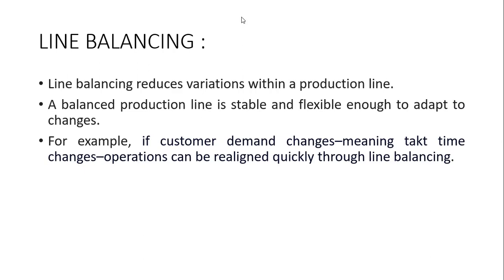According to the external demand, we have to fix the cycle time constraint for an assembly line. For example, how to calculate the cycle time: the projected requirement divided by the number of shifts to be operated. The projected requirement is the expected demand as per the customer's statement. Based on that, we want to realign the assembly line sequence in order to operate all the production tasks according to the fluctuation in customer demand.